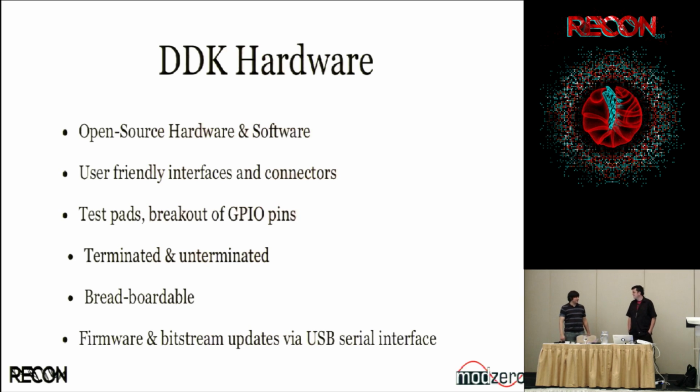I'm getting the multimeter, and I'm measuring the voltages. Which is, by the way, for those who don't do electrical engineering, the first commandment of debugging electronics: thou shalt measure voltages. So we got out the multimeter. We started measuring the voltages on the test pads. And basically, it turned out that Thorsten's USB hub was providing 3.7 volts instead of 5.